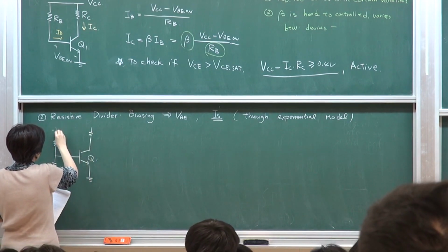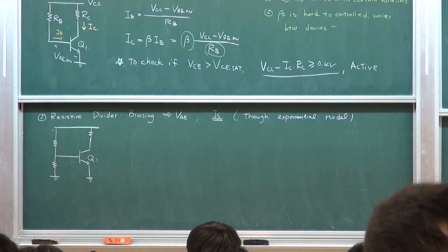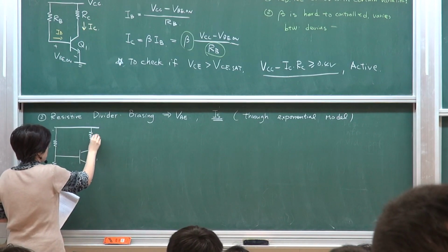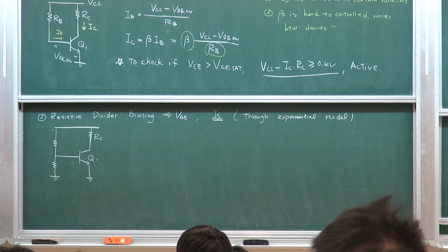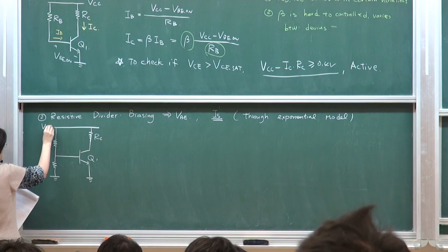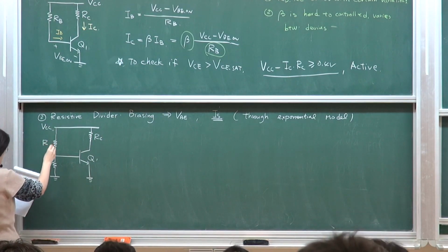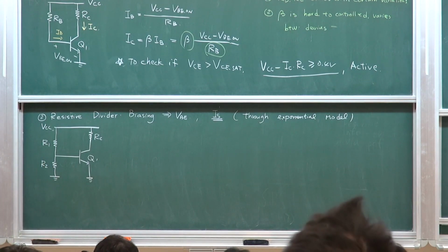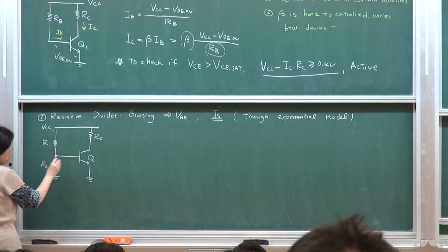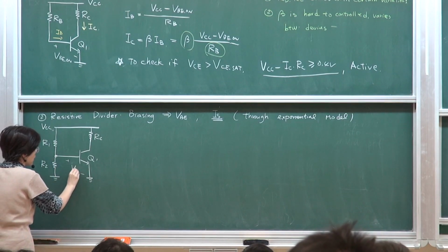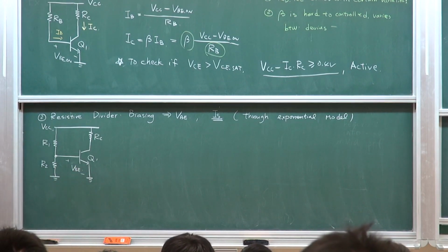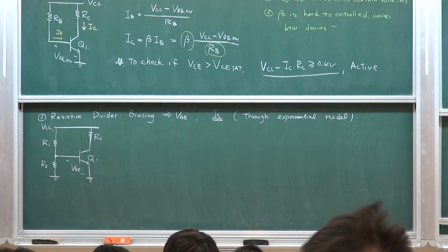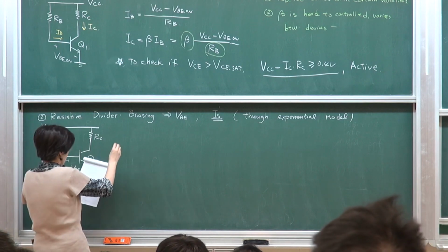So this is also a common collector, common emitter structure circuit as an example. What we actually use is the supply voltage, with a very simple resistor divider type of circuit, and then set this particular point. Through this divider, I'm setting up VBE as a voltage biasing system. Okay? So we can make some assumptions first.